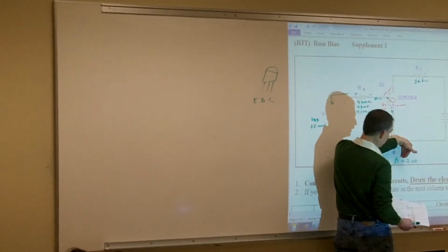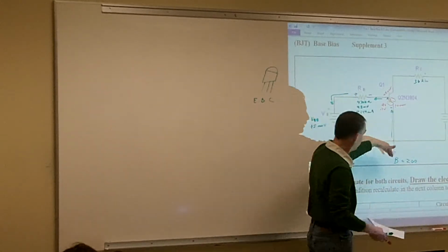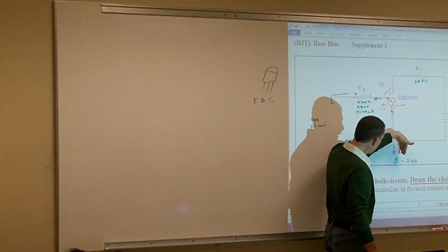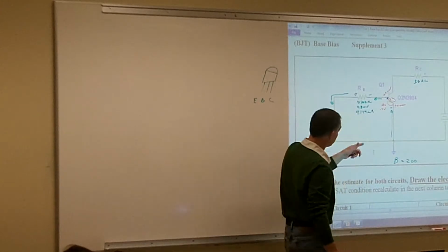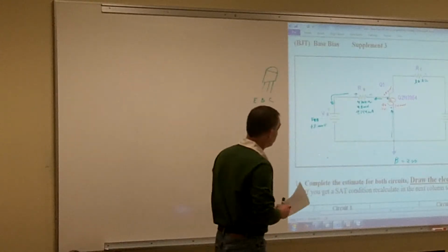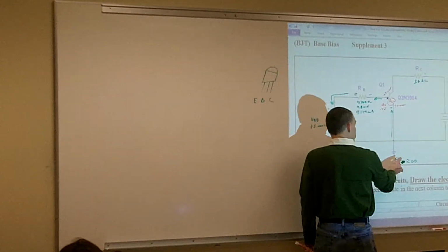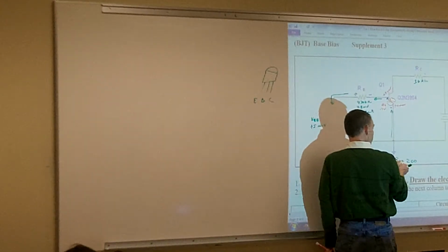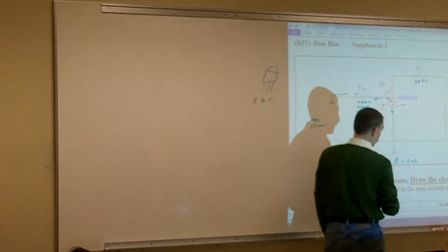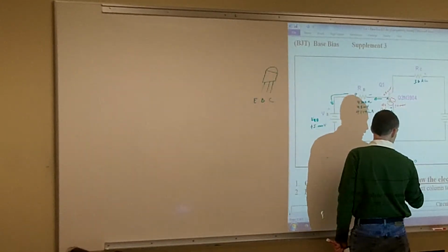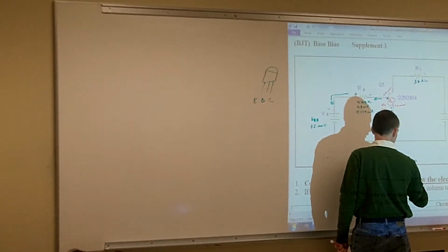We're going to use what we call our curve tracer, just like we did with the diode, our 2-wire diode curve tracer. We're going to do the same thing with the transistor, and we'll actually be able to calculate out exactly what our beta is going to be for our 2N3904. But on the data sheet, it's going to be anywhere from 100 to 300. When you're looking on the data sheet, this beta is typically our beta DC.